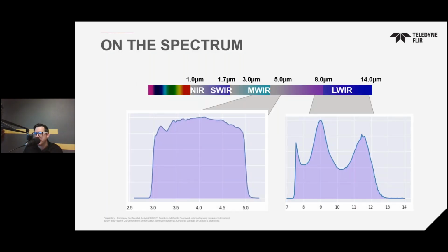So moving on, the exact spectral response that a detector has is very detector specific. For the vast majority of applications, typical detector responses that are representative of a given detector model, like you see here, are extremely useful for things like considering options for spectral filtering, selecting an IR window material for an environmental chamber or blast chamber that you need to view through, and you want to make sure it's compatible with the camera that you're using, or performing custom calibrations and so on.